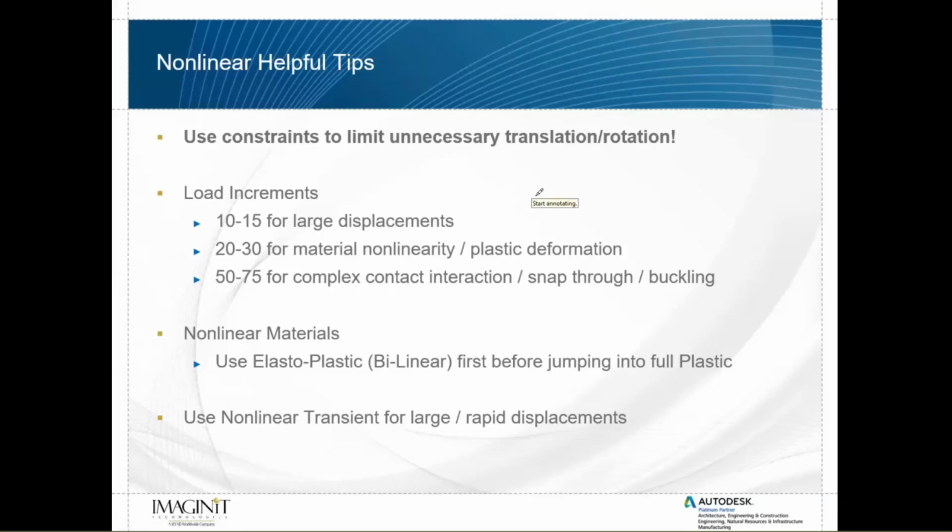Load increments are also very important. When you run a nonlinear static analysis, you have to specify a number of load increments. These are just guidelines. I wouldn't take this as the holy grail of load increments for Nastran, but I have found in the past that when you're looking at large displacements, and let's say that's your only nonlinear condition, so you don't have new contacts being created and you don't have any material nonlinearity, and the only thing you're observing is a large deflection in a part, you're probably only going to need 10 to 15 load increments. It's fairly easy for the solver to calculate that.